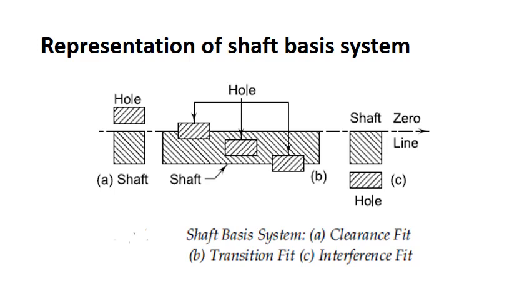See, the tolerance zone of the hole is well below the tolerance zone of the shaft. So again, we need to apply external force or pressure to create the fit. And figure B obviously is the transition fit. Please take your time to understand the different types of fits from this tolerance zone representation.